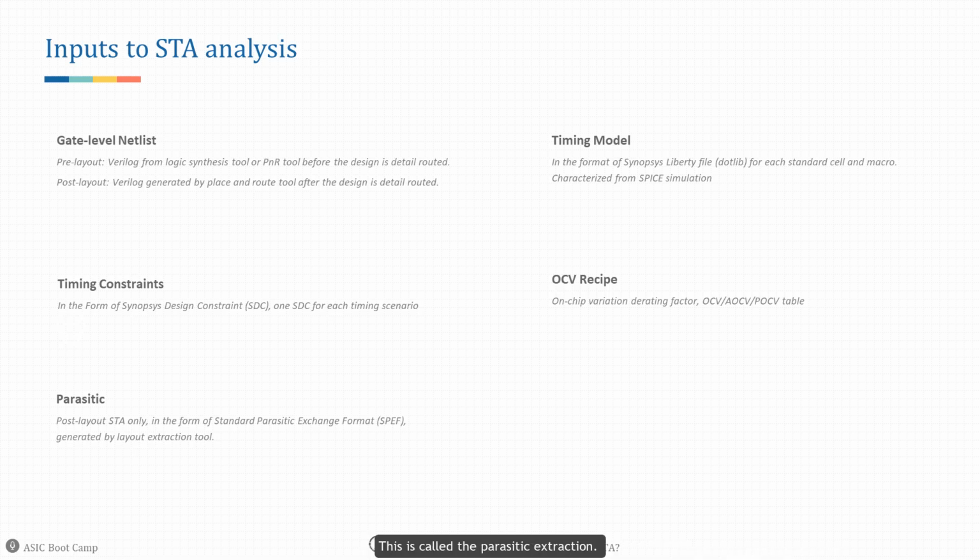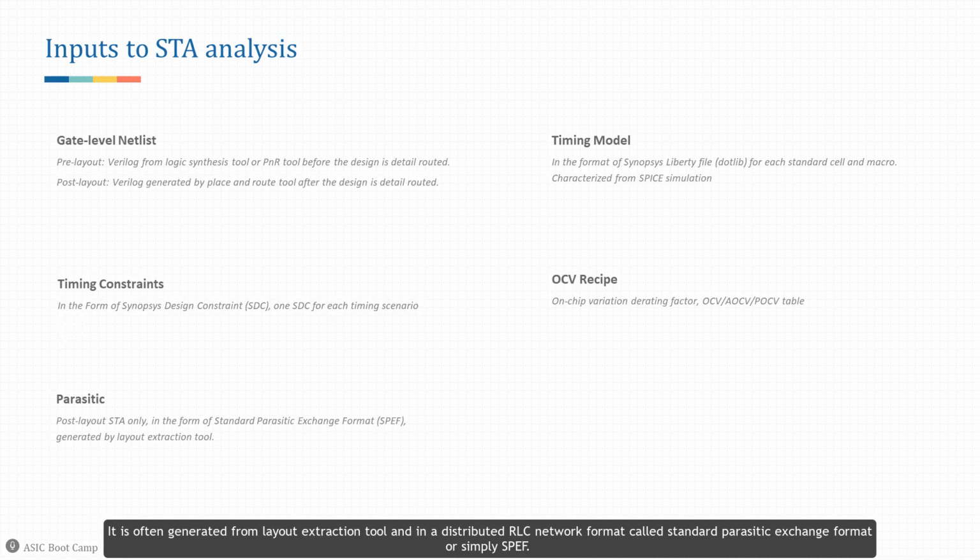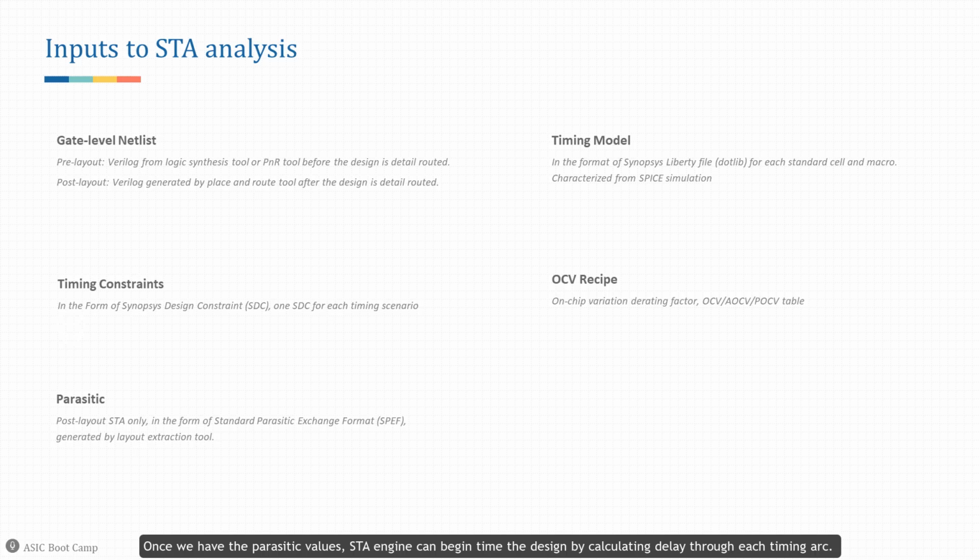This is called parasitic extraction. It is often generated from a layout extraction tool and in a distributed RLC network format called Standard Parasitic Exchange Format, or simply SPEF.